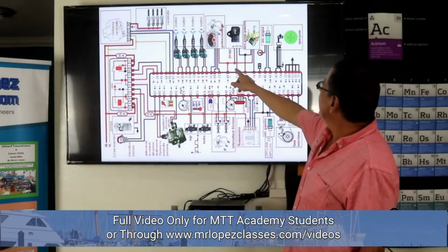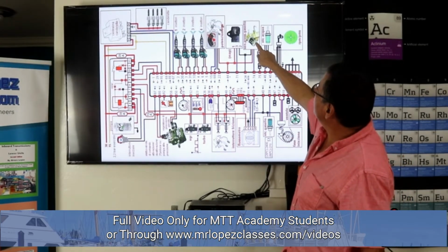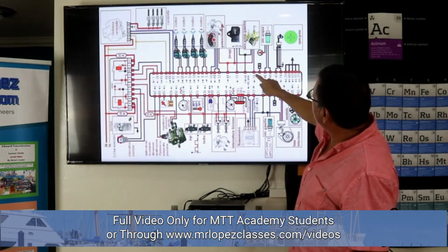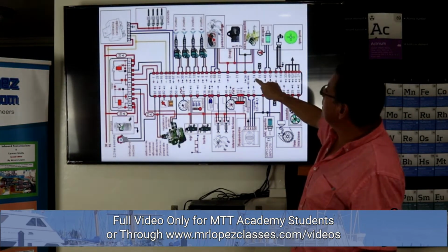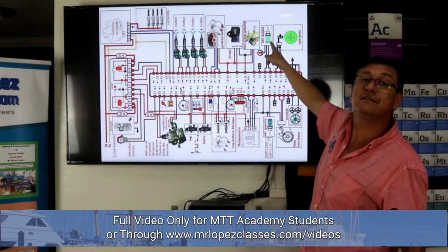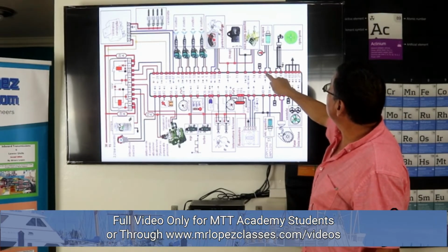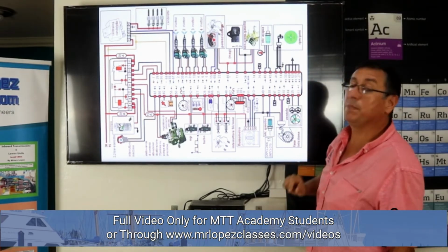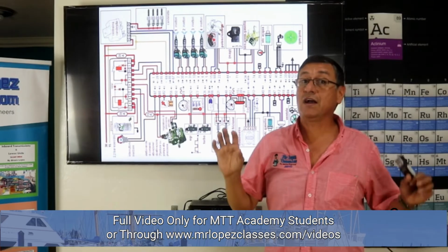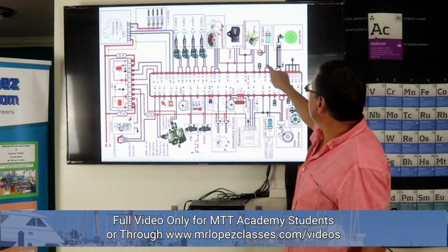Marvelous. And the other one, the pressure regulator at the common rail. The signal is coming from pin number 74. This is the coolant temperature sensor. This is the ground. This is the signal. The signal is in pin 46. If I have a code related to coolant temperature, the sensor is located at pin 46.